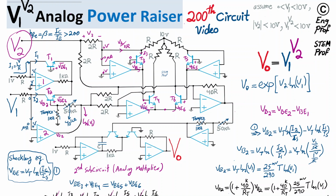The same idea here. Here we have 0 volt, so that 0 volt is present here. And we have 10 volt, so basically the voltage drop across this resistor R is 10 volt. So the current that is coming is 10 divided by R. Therefore, I3 is the sum of V2 divided by 2R and 10 divided by R. So I'm going to write it quickly here.